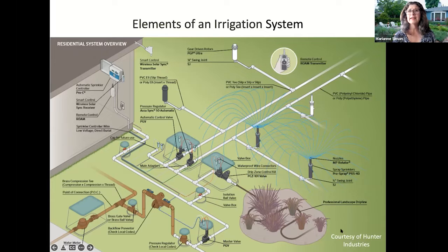And then after that, you are out to the specific delivery method. So at that point, you're either watering via spray or you are watering via drip. So that's the big picture. Oh, you know what? I forgot the controller. So basically, you have the mastermind on the timing of those valves. And we'll be doing a separate sequence on that after this module.